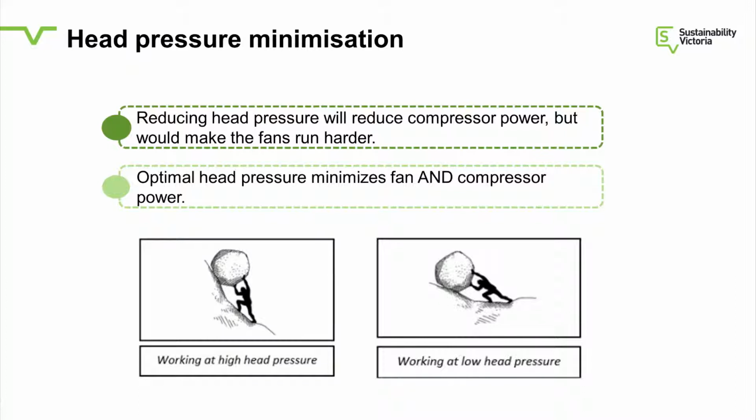Now, if you set that pressure too high, then the fan will cut in very late, and your compressor will run at a high head pressure always, because it'll always wait for that pressure to build up before it turns on. Now, why would anybody set it like that? Well, this could be because there might be a fault with the expansion valve. Remember I mentioned the expansion valve needs to have enough liquid pressure. If for some reason the contractor might have put a very small expansion valve in there, how does he fix that? Well, he can either replace the expansion valve, or he can set the head pressure high.